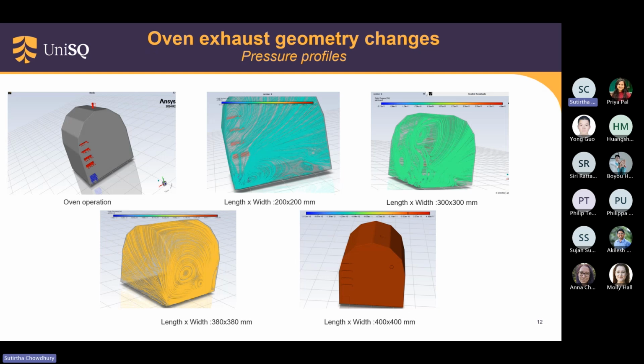Afterward, when we made the chimney size 300 mm and ran the simulation, we saw the pressure profile going positive, but it was not enough, because you can see from the temperature pressure contour line that it still lies in negative pressure.